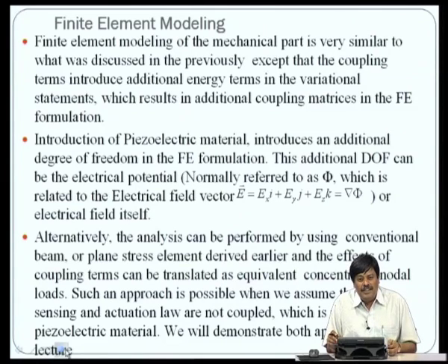So, what does it mean in the finite element modeling? The introduction of piezoelectric material introduces an additional degree of freedom, which is in the form of the electric field E. This additional degree of freedom can be an electric potential phi, which is related to electric field E by taking the gradient of the potential phi, or we can take the electric field itself. Either way it is fine.